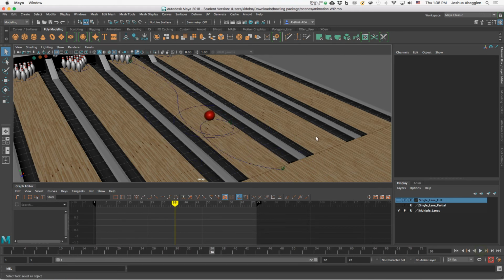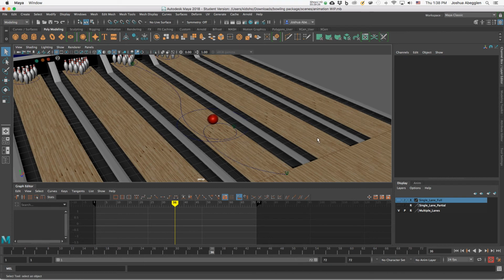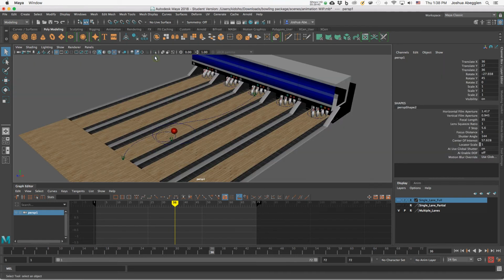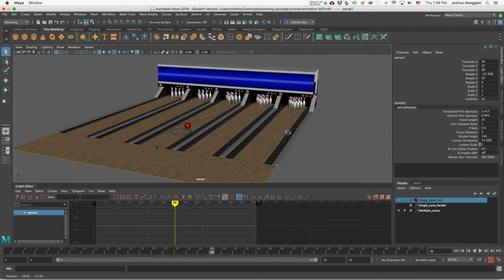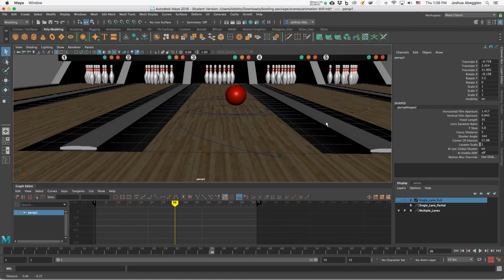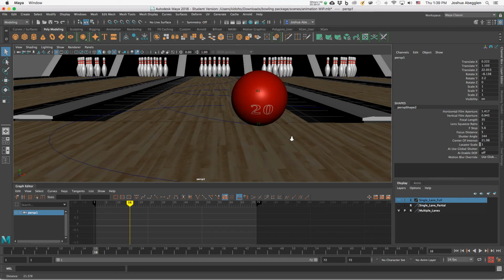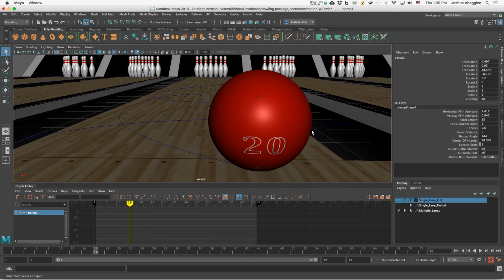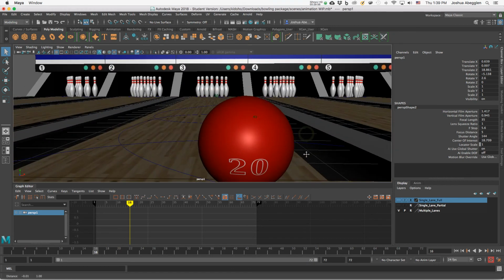All right. So the next thing that I'm going to do is talk about animating cameras. And instead of animating this camera that I'm currently looking through, I'm going to create a new custom camera specifically for this application. I'm going to start by clicking on Panels, come down to Perspective, and choose New. All right, and so now we have this new camera, and we're looking through the camera. We're moving the camera around in the space, and something that I'm going to do is show you guys how to establish a little bit of a novelty shot with this camera.